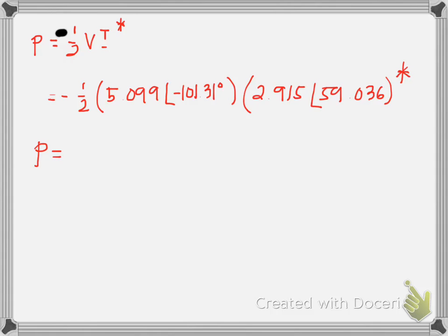we have negative 7 minus J 2.5 VA, where 7 is the real number, the real power. We have 7 watts, and the complex power conjugate, the imaginary part, which is the reactive power, in var we have 2.5 var.